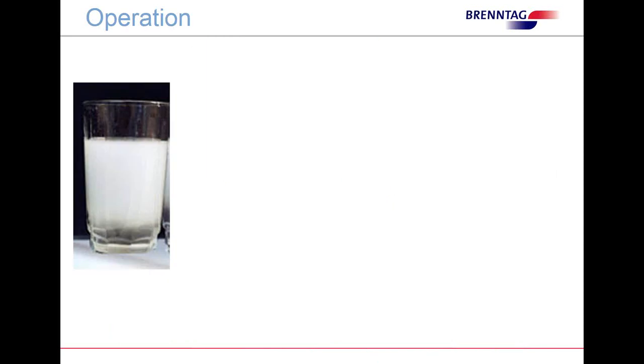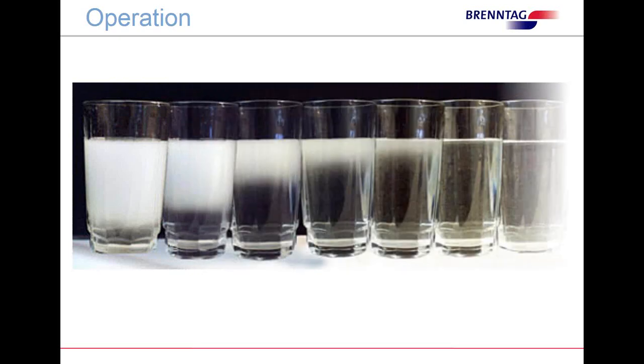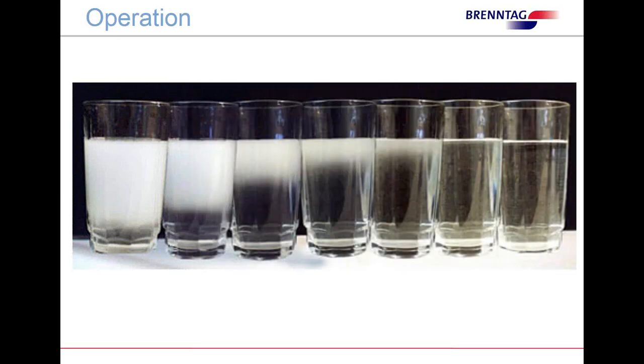This next slide, I think, is very helpful understanding the rise of air in a DAF unit. Here we see, again, we talked about the spigot, the faucet in your kitchen in the summer, and how there's air entrapped in the water. This air now will rise very slowly, bringing the particles of oil or particles to the top of the DAF unit. So I think this is really a great picture showing exactly what the DAF airflow should look like coming to the top.